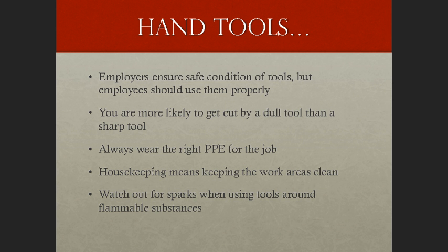Employers should caution employees that saw blades, knives, or other tools be directed away from aisle areas and other employees working in close proximity. Knives and scissors must be sharp. Dull tools can be more hazardous than sharp ones. Appropriate personal protective equipment such as safety goggles and gloves should be worn due to hazards that may be encountered while using portable power tools and hand tools.